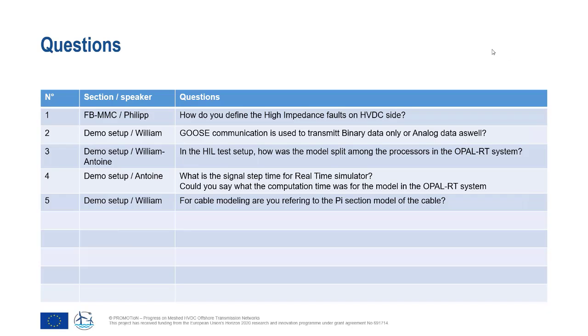Okay, thank you very much for the question. I'm not sure what is meant by define the high impedance fault. Maybe I can give some insights on how to treat low impedance and high impedance faults and where the differences are for the full bridge protection strategy. First of all, a high impedance fault is for us a fault in the order of 20 ohms.